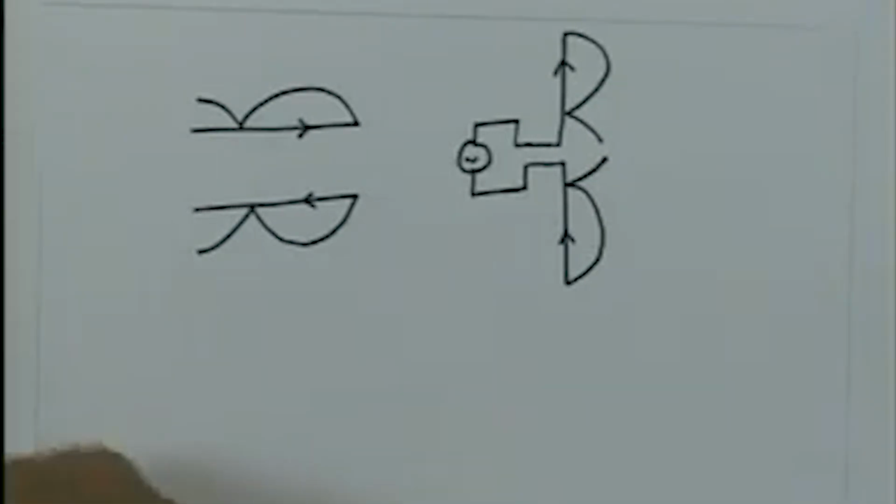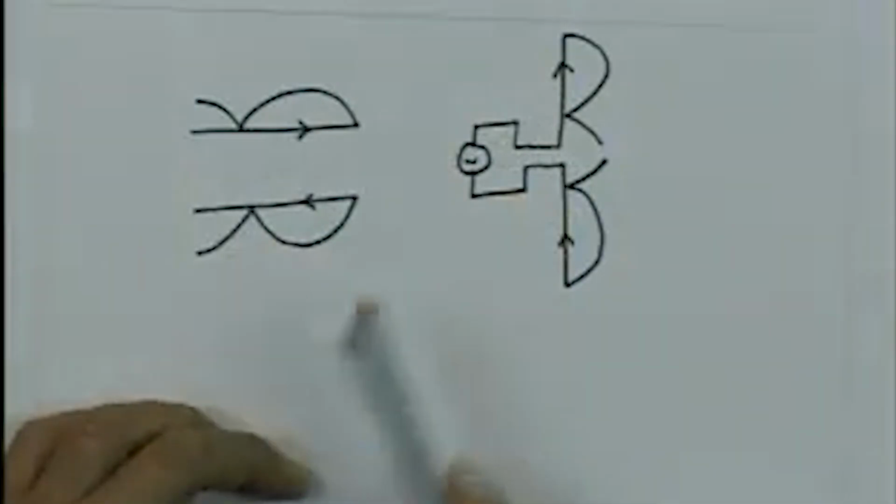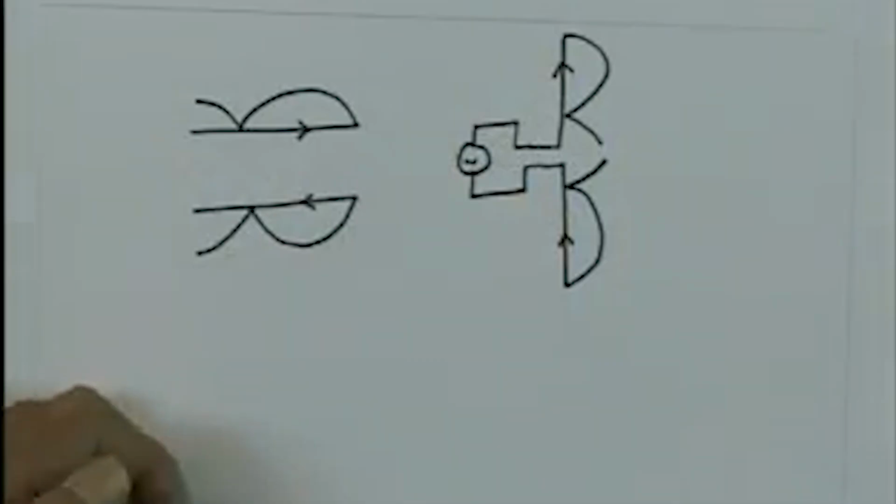Now, of course, at this point it is not very convincing that when the transmission line is completely flared up, the arguments like standing wave patterns and all are still valid. But it so happens that even the rigorous solution gives you the same kind of current distribution as you would have got from the standing wave pattern on a transmission line. So, essentially now we know the current distribution, and a few logical tests we can conduct on the current